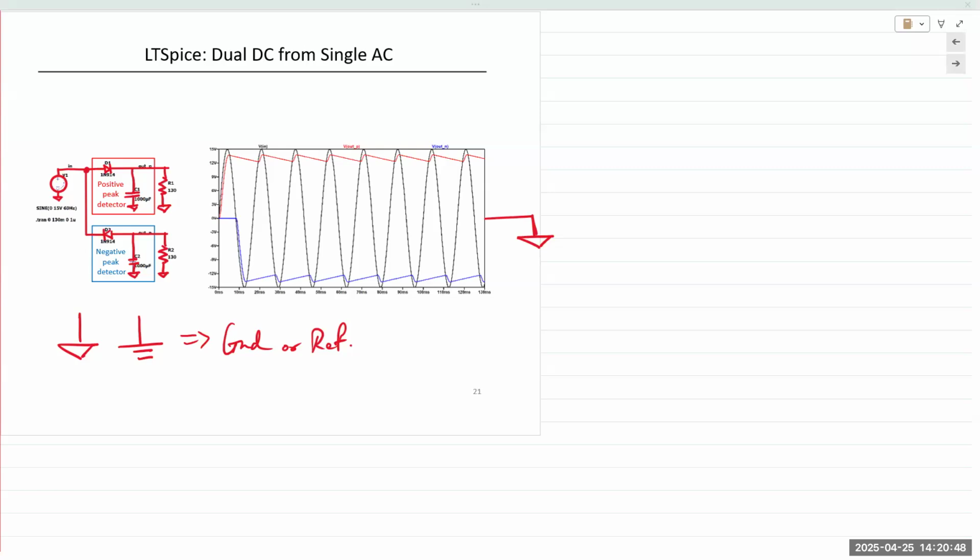You remember lab 1, the output of the 555 timer, we had a diode and a capacitor, D1 and C1. Sorry, we had a clamper circuit first, D1 and C1, and then we had a peak detector circuit, D2 and C2. So D1 and C1 in that lab were the clamper circuit, and the D2 and C2 combination was the negative peak detector circuit. And so that's what we have here.